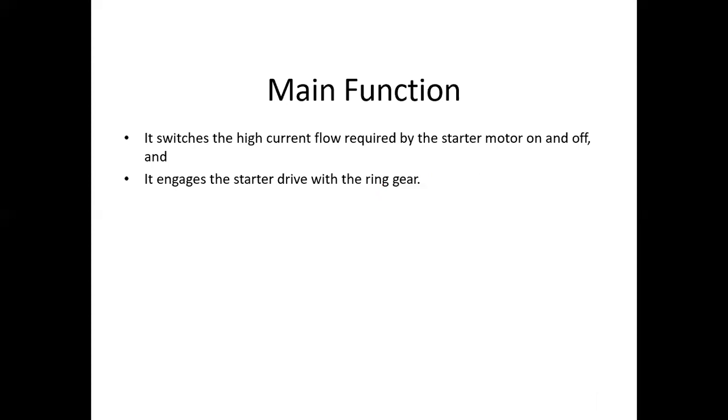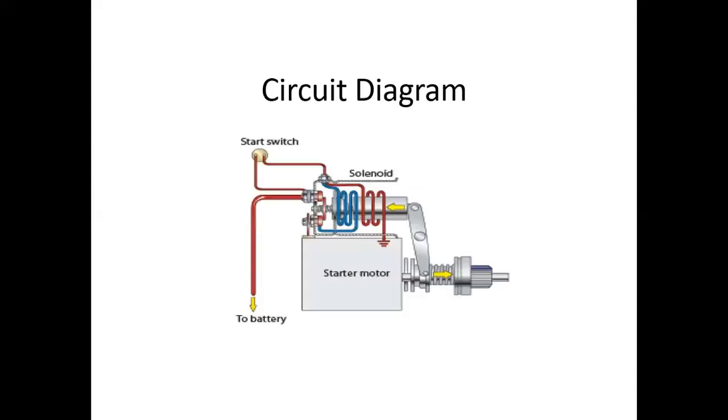The main function of the solenoid switch is to switch the high current flow required by the starter motor on and off under the required conditions, and to engage the starter drive with the main ring gear. This is the main function of the solenoid switch.